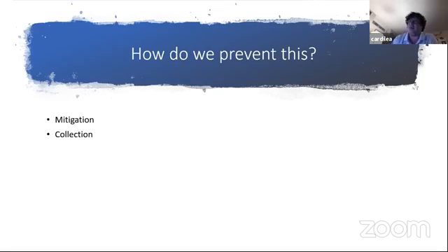The two ways are mitigation and collection. Mitigation is simple housekeeping. That's when you have a relatively minor dust explosion. That's basically sweeping, vacuuming, hand vacs. And I know she showed in the video that guy blowing the dust off of machinery. There's ways to safely do that. Obviously, you don't want to just blow the particles into the air, but if you go from top to bottom, you can knock down the dust.